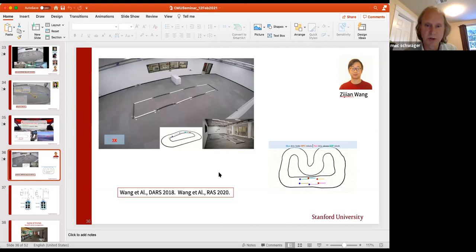So there's no communication between robots in any of the racing work that I showed. The idea is that every robot is doing all the computation for itself and the other robots. You could see this as a way of predicting the trajectories of the other robots. This is an intention inference sort of method. So I am predicting what the other guys will do under the assumption that we all will settle into a Nash equilibrium. And then they're doing the same thing.